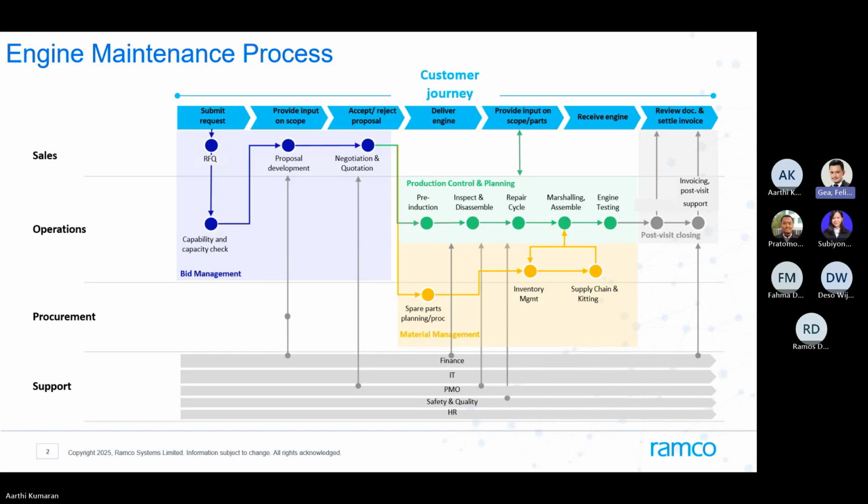That begins with some documents that you may receive from a third party or from Baroda for that matter, for the particular engine serial number. The details of the configuration is basically the template, the sub-assemblies that are expected to be attached onto the serial number while you are receiving it. That's what we may call the expected configuration, the template of the engine when we receive it. And along with that, you may receive the details of your parameter values, your life limited parts list, their respective usages, any replacements that are required, service bulletins that were probably complied with earlier, and also a set of service bulletins that they request you to comply with for that particular visit, right?